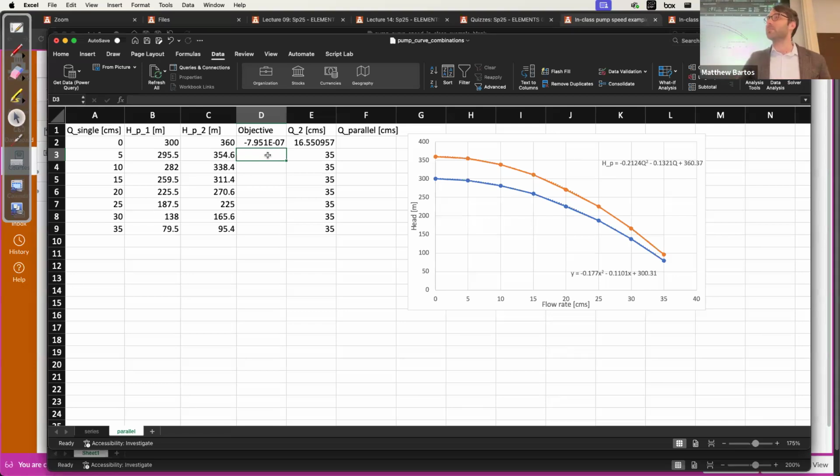So why is this maybe not the best method for solving these discharges? Some of you might have run into this issue. Yes. Yeah, it can give you the wrong root. There are two valid discharges for this polynomial. So a better approach would be to use a polynomial root finding algorithm and then select the positive root. Unfortunately, Excel does not have a polynomial root solving function. You can do this using Desmos or your graphing calculator, or Python and MATLAB if you're comfortable with those programming languages, to find these discharges.